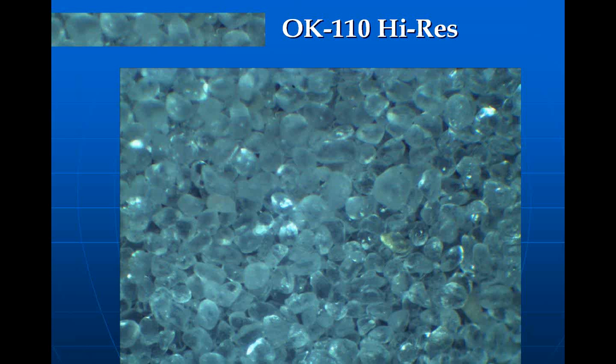Every slide I show you at low res, pixel to pixel, is exactly the same resolution. So these slides are comparable. And you can see even within this OK110, there's a large particle near the middle, slightly to the top right, that is probably 150 microns, and there are some 75 micron particles in there. But this is what OK110 looks like, and I've got a test strip at the top so you can get an idea.